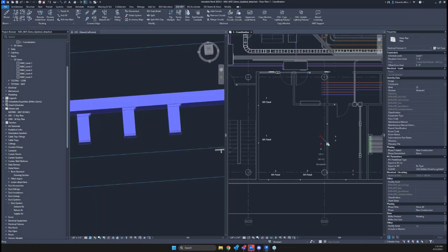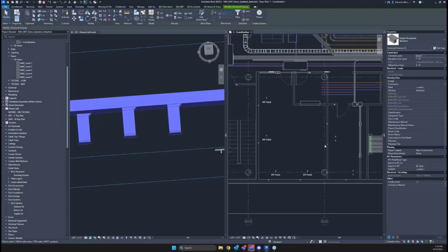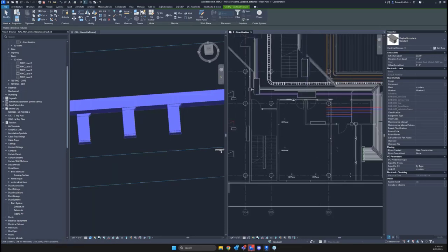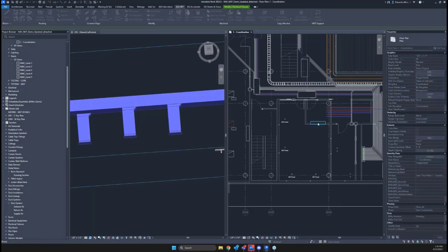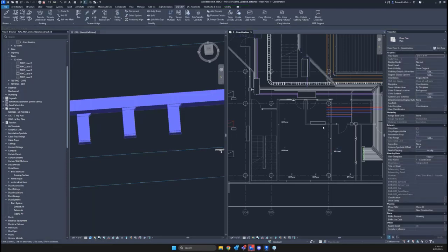The idea is that sometimes I want to grab multiple elements, and I want each of those elements to get circuited to this panel as an individual circuit. To do this in Revit, you actually have to click each element, power circuit, then go to this one, power circuit. Well, what we're saying is grab as many of those elements at a time as you would like. MEP, create circuits, choose my panel, and we'll find that those were both created as unique circuits onto that panel. So a really easy way to start taking a group of elements and giving each of them their own circuit.